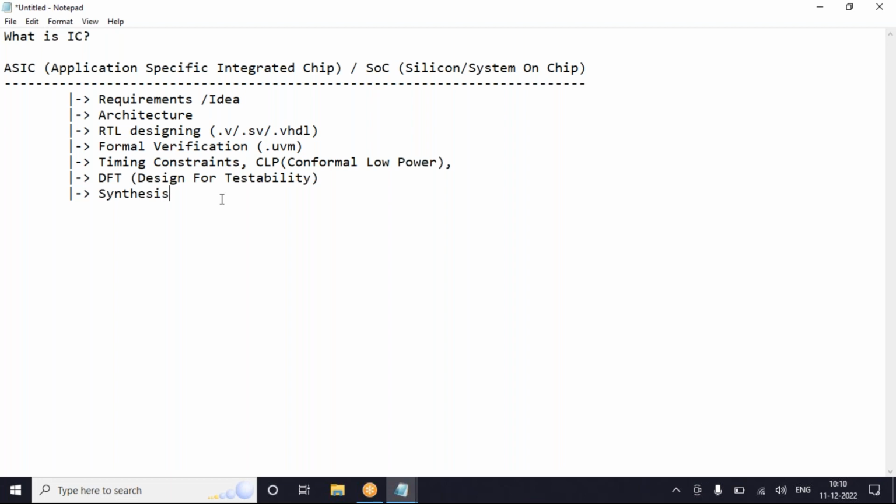That means, as I said, module, always at, assign keywords, those will be converted to their equivalent gates. So for example, always at posedge of clock. What will that particular cell be representing? When we just say always at posedge of clock, what will we represent it as?